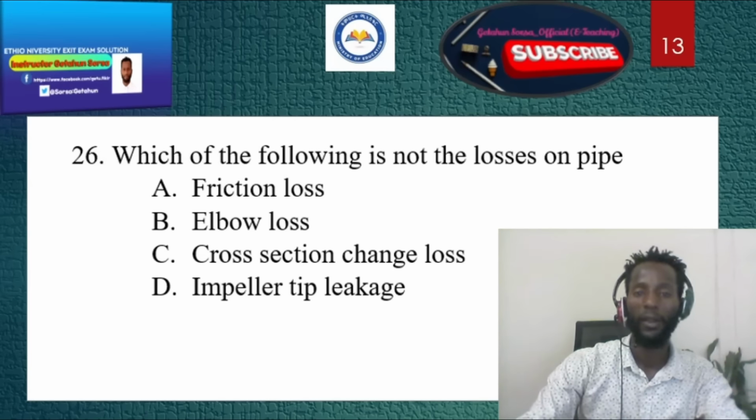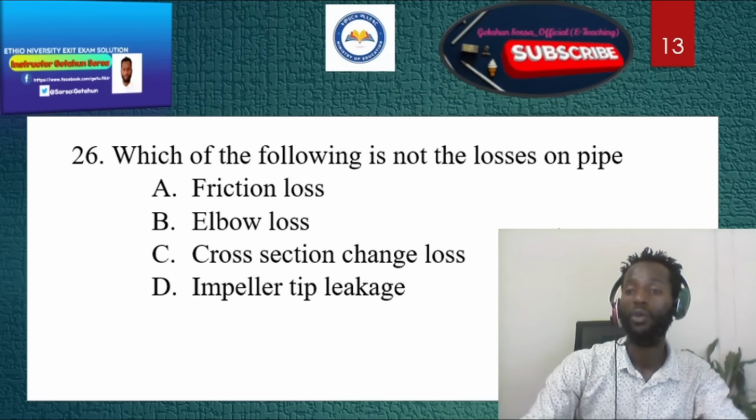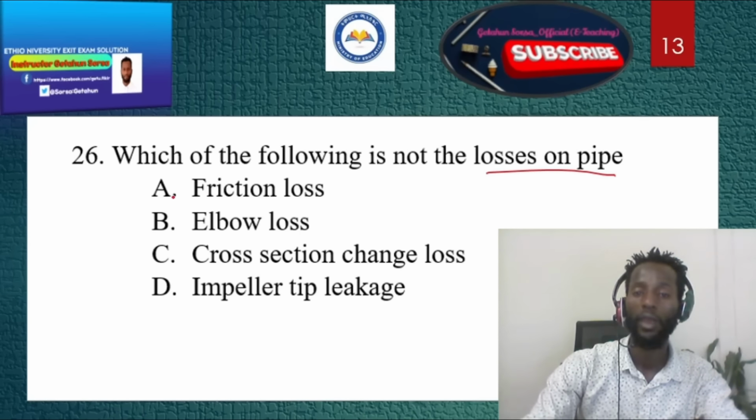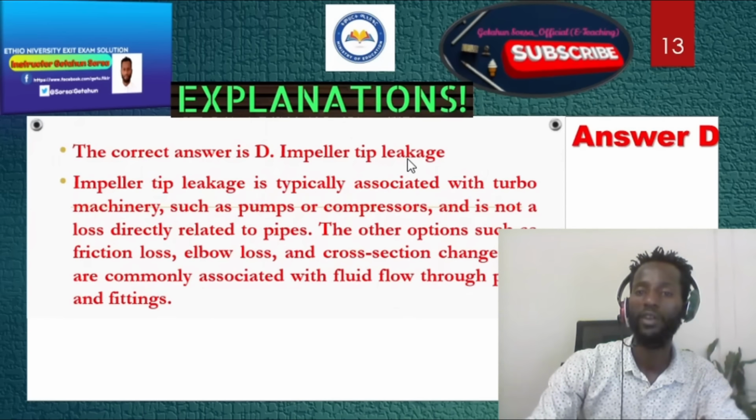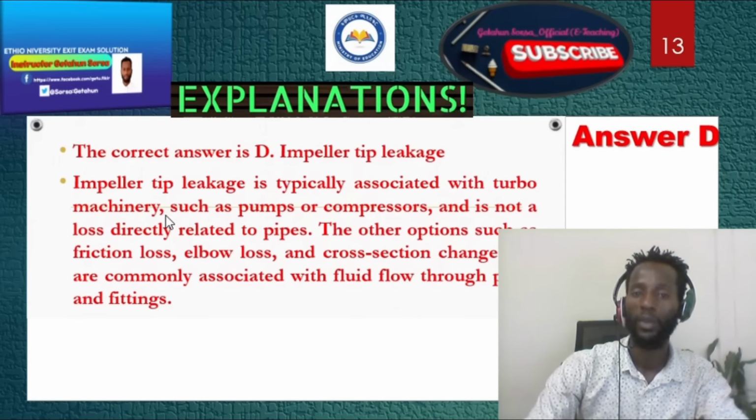The next question is, which of the following is not a loss in a pipe? A. Friction loss. B. Elbow loss. C. Cross-section change loss. D. Impeller tip leakage. So this is not a loss in a pipe. To choose the correct answer, we also have to see the explanation. So the correct answer is D. Impeller tip leakage. This is not a loss in a pipe.